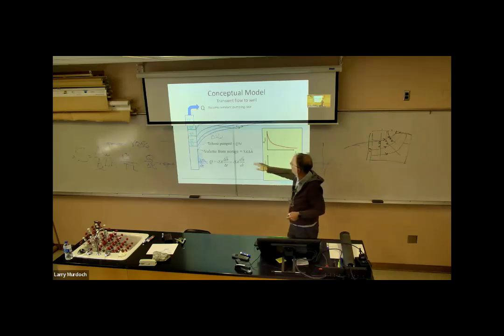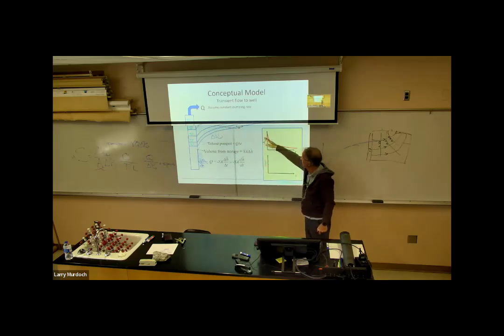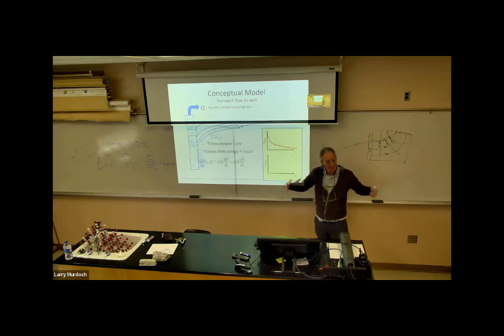Okay, so as the radius of influence increases, this slope can flatten out. So that gives us a curve that looks like that. It's qualitative. It's decreasing to release the water from storage, and the slope of it is flattening out because the area is getting bigger. Okay, see how that works?